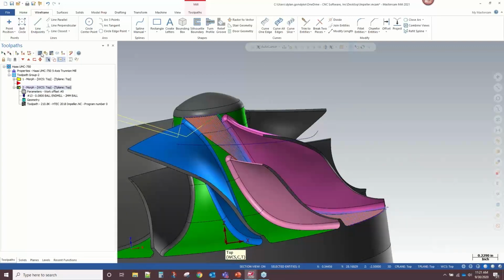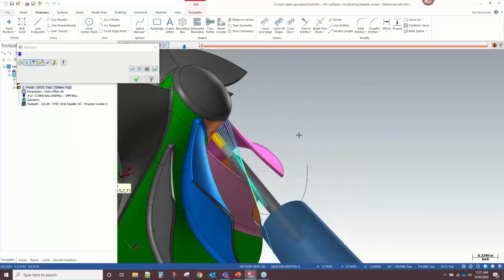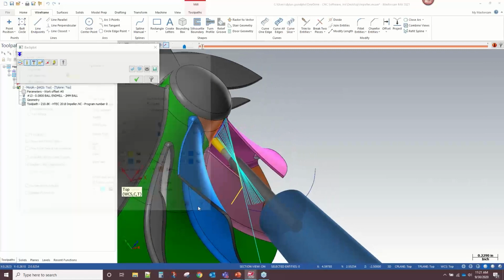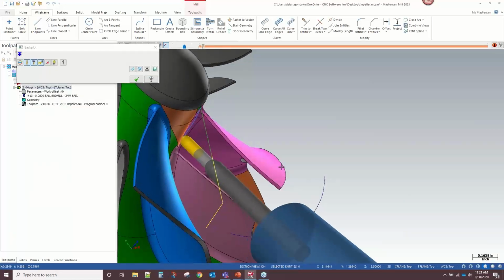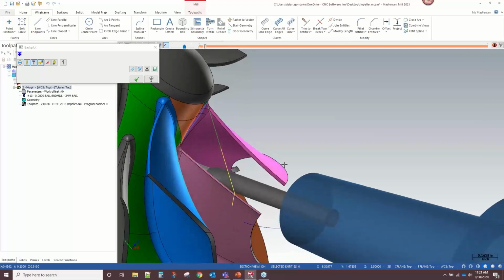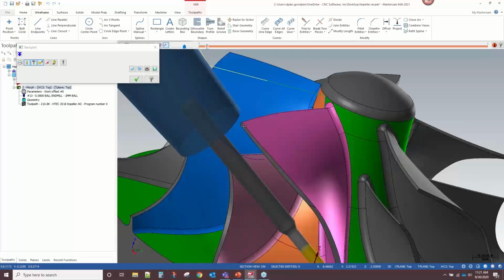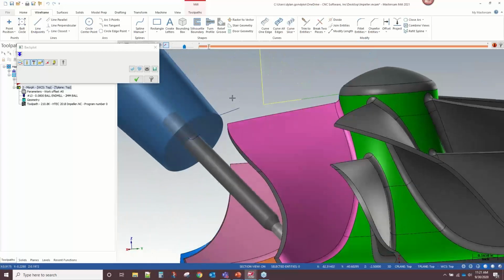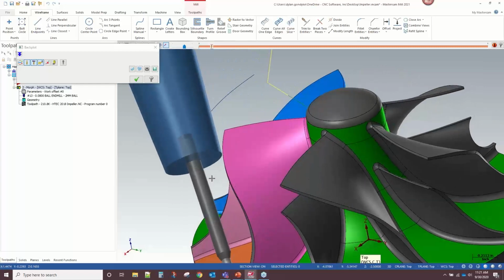So this is the toolpath we get. And let's check out that transition through the throat area. And let's turn off these vectors so we can see this properly again. So we properly come down through the center of that throat, and we avoid everything. And we clear the holder, and then we sweep out to the end of the floor.